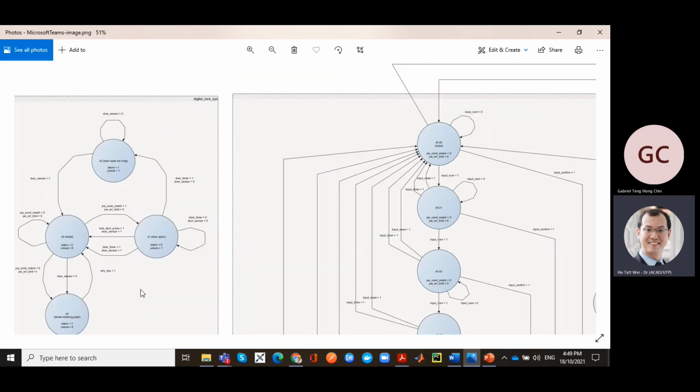So if you really want to tighten this up, which is not a necessity, it's just functionality, it's up to you. You can actually have a signal coming out that if sensor equals 1, you force any state to come back, because when sensor equals 0, this is open, right? Because you only look at the door sensor when you're in the open state, right? So sensor 1 means closed. Yep, so door sensor 1 is closed.